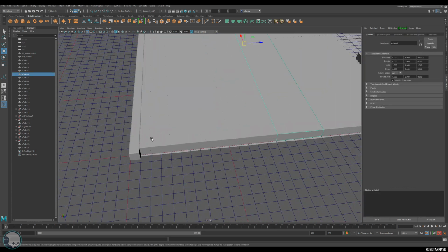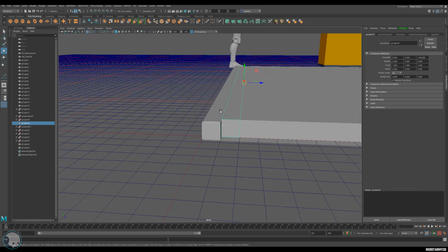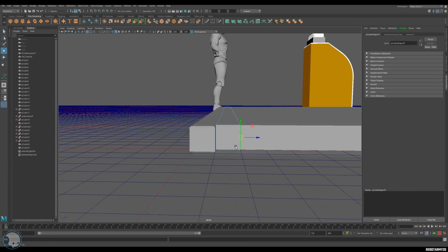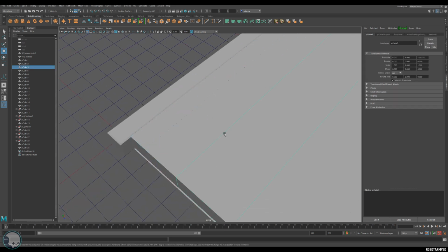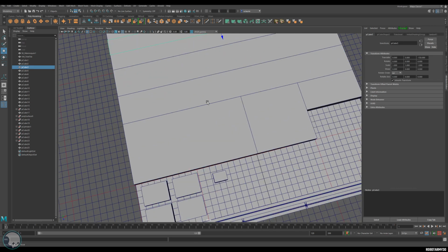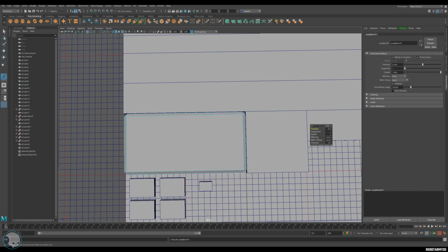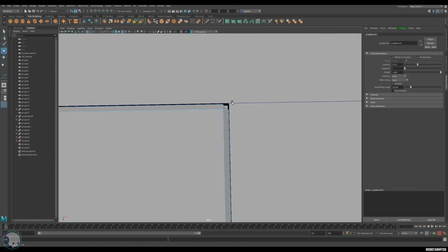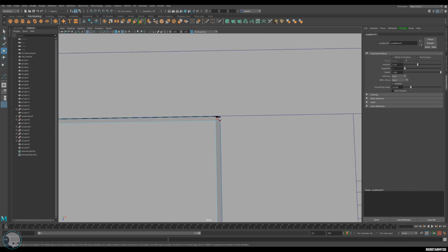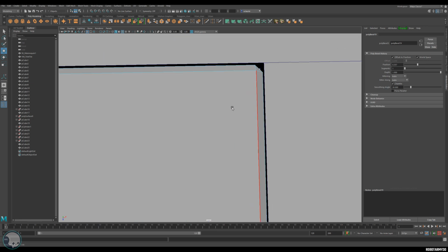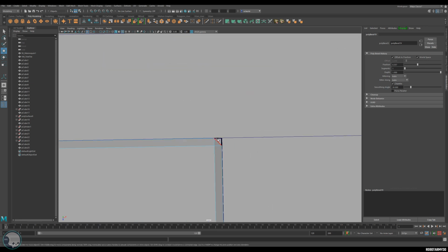And next I'm going to come back over here and I'm going to bevel some of the edges of these ones again. So normally I don't bevel these edges here, because what happens then is if you've got a few blocks together, if we come down here, say to these, if I bevel all the edges, which you'd normally do on a panel in 3D, what you end up doing is having this hole here, and that can kind of show up if you're not super neat with your polys, and oftentimes you're going to be mapping this to a single poly. So what you'll end up having is this blank area in the corner of your poly.